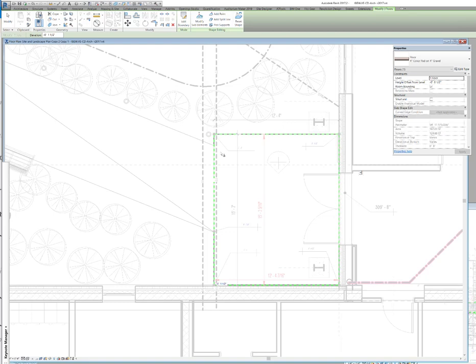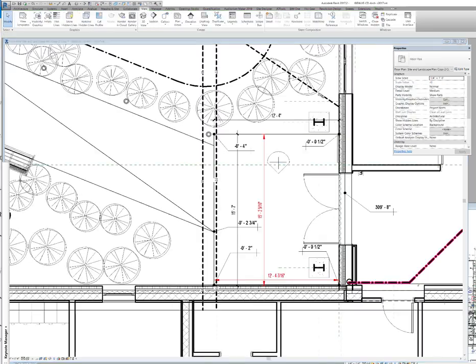And then this point here wants to be 1/8 of an inch to the foot below this one. This is 15 foot 2, going to round it to 16 feet, that's 2 inches down, this should be -3.5, bingo. And then this is at 0, so this is kind of ready to go and ready to detail. So if I come in and elevation tag around it, I'm going to find that these are the elevations relative to the first floor. Not the way you want to leave it, we're not going to leave it that way, it's a handy thing you can do later.